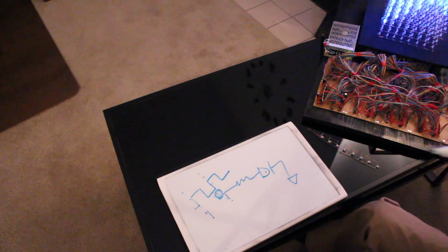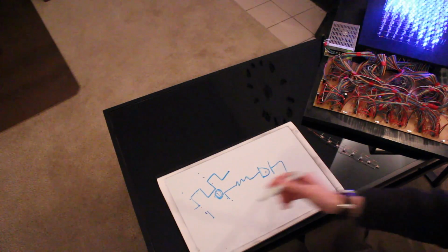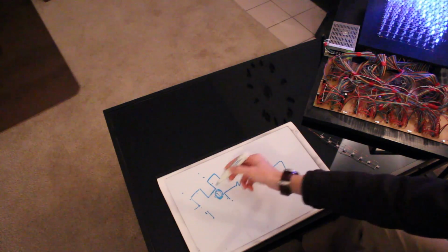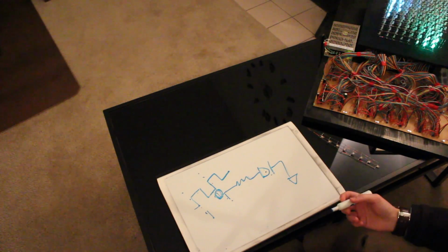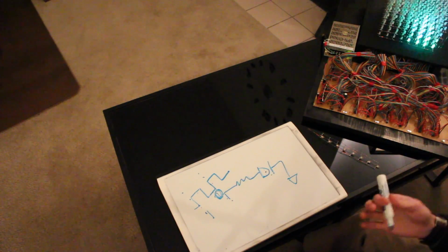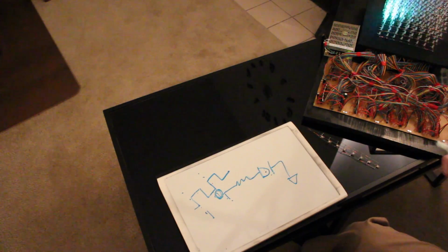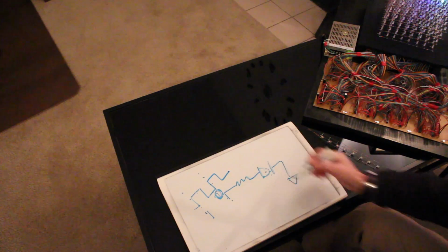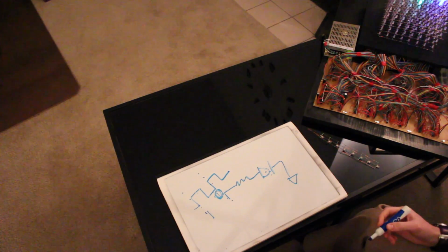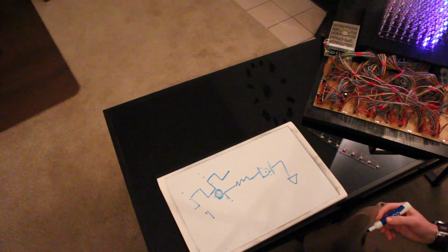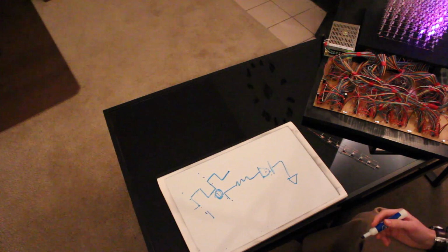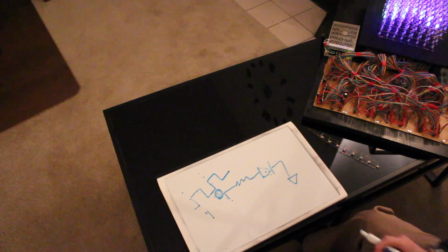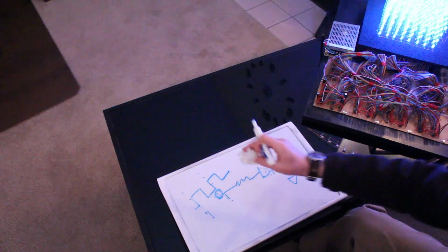And when you first see this, looking at it so zoomed in, you think, how could you not notice the LED turning off? I mean, we would notice that, right? No, it's so fast that you cannot tell that it's actually turning on and off. Your vision just perceives this as dimming the LED. So it's kind of cool. And the Arduino PWM outputs are pretty slow, actually. I think they're less than 500 hertz. I think I'm running my modulation over here in the kilohertz range. I can't remember off the top of my head, but anyway.